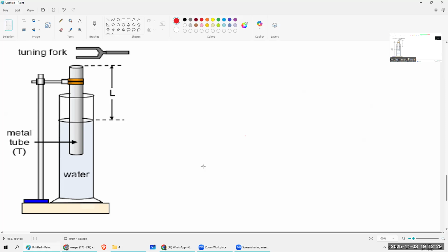So the way this one vibrates at a specific frequency region, between 638 hertz, this one also vibrates at the exact same frequency. So if I hold it over here, the entire board material also vibrates at the same frequency. This one works as an amplifier. This is the same thing that is done using the hole in an acoustic guitar.